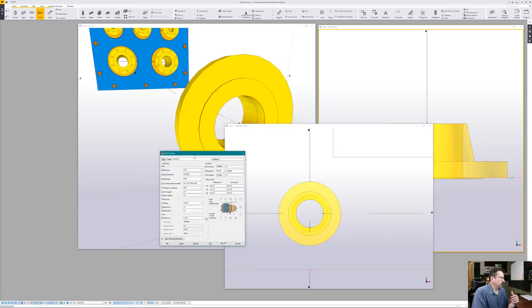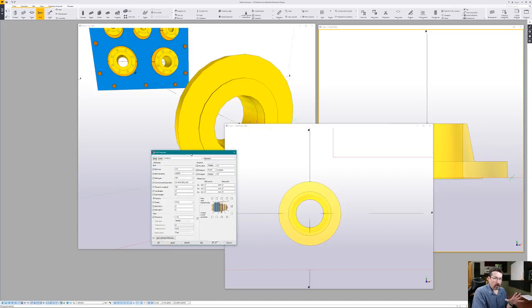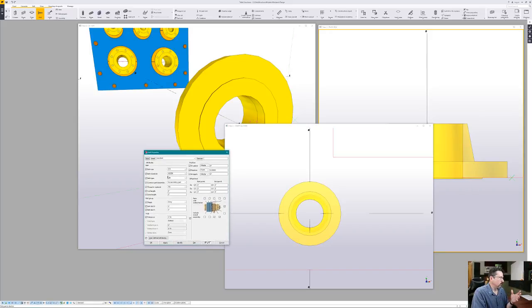Now the bolts that we're using here, we're just doing holes. We're not doing the bolts themselves. I want them to be 3/4 inch, so I'm going to select the 3/4 inch. Since we're just doing holes, I don't think the bolt standard or the bolt type matters. The threads and the material don't matter. For the cut length, you just want to make sure it's at minimum 2 times the thickness of whatever you're trying to go through. The default is 4, and we're good with that. The shape and the bolt group we'll get to in a minute.